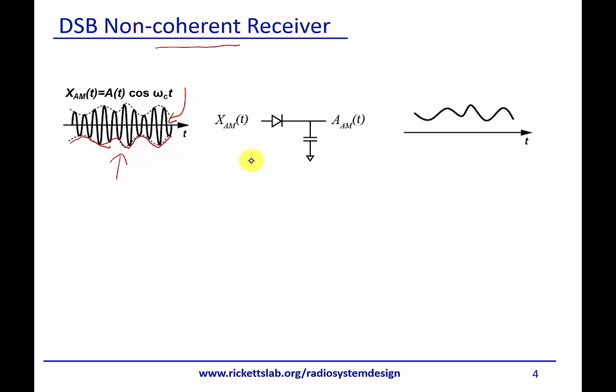And so a very basic one is a simple rectifier, where we're just peak detecting, and you can see where this just peak detects and we get our signal off the back. Now if you use this circuit exactly as it is, you would just have a DC voltage on the top here. In reality, there is some load off here that discharges the cap so that the signal can fall over time. But the basic idea there is we're just doing a peak charging. And this is nice because like I said, we don't need to know anything about the carrier.